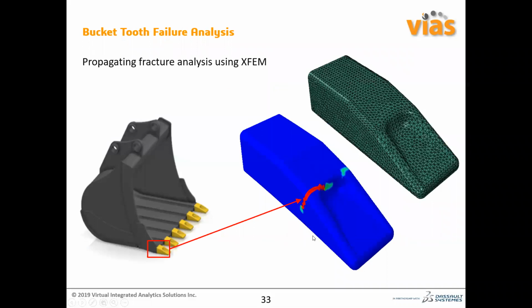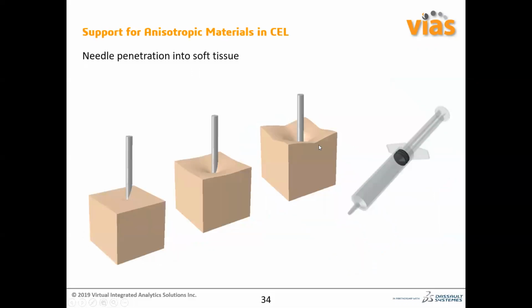And this is one scenario where you want to capture fracture mechanics. It's the extended finite element method, XFEM. This is not a mesh-sensitive approach; it is actually a mesh-insensitive approach. When you have a backhoe or a crane with repeated loading, or even if you are applying a huge amount of loading, the fracture can propagate in a certain fashion. You can use XFEM technology to capture that kind of fracture propagation scenario, as you know, and to find out what will be the life of that particular kind of tooth.